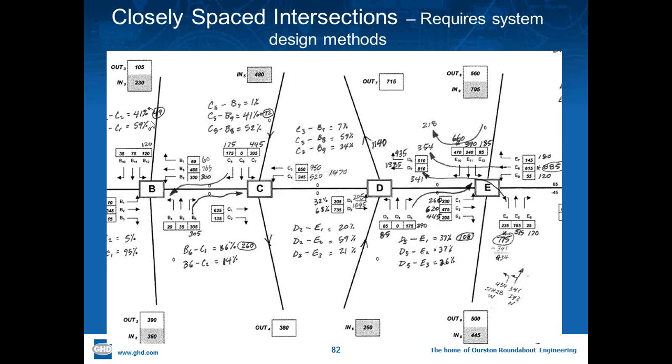And this diagram was prepared to look at different origin-destination patterns to understand the flows between the nodes and the ramps downstream. If you simply were to take the turning movement diagram, you wouldn't know the origin of that traffic that enters this lane. So it's vital that we understand where this traffic comes from. And there are different sources. This left turn volume could come from a through movement upstream, or it could come from left turns from the side street or the frontage roadway. The left turns from the ramp could end up down in the right-hand lane or in the left lane. It could make a left turn at the frontage road.